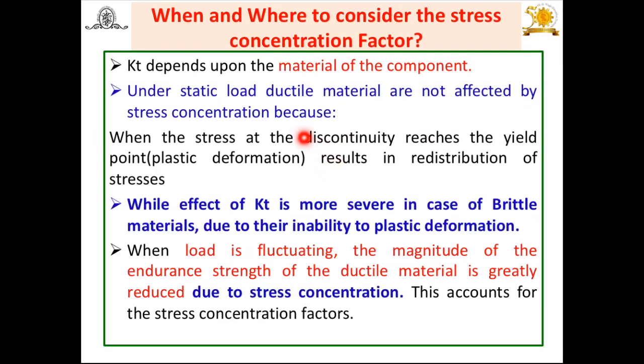Now, when and where to consider the stress concentration factor? As already discussed in an earlier slide, stress concentration depends upon the material of the component. And under static load, what will happen? Ductile materials are not affected by stress concentration. Now again, try to understand: while designing the component, there are two criteria. One is static, another one is dynamic. In static, again, whether the component is made up of a ductile material or a brittle material. If it's made up of a ductile material, no need to consider the stress concentration.